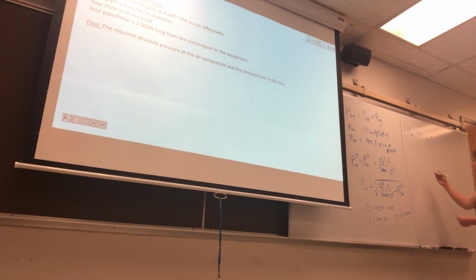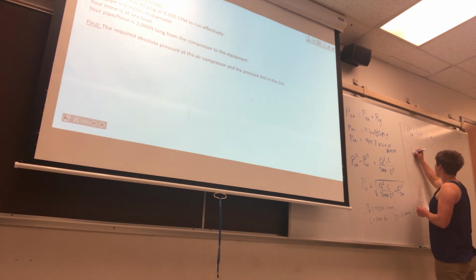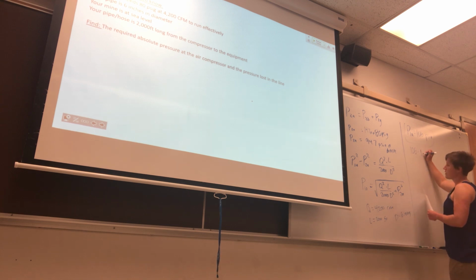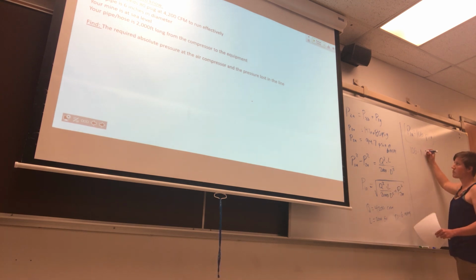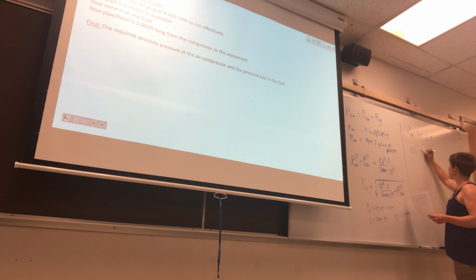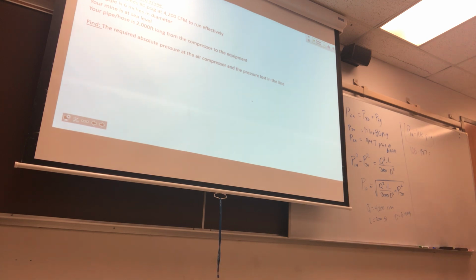Okay, so that 106 minus, again, that 14.7. What do we get with that? 91.3 PSIG. Okay, so that's the reading at the compressor.